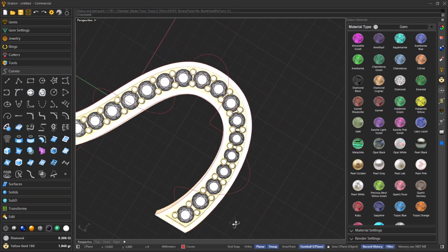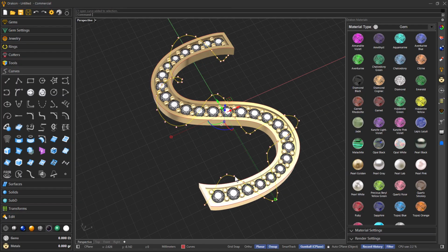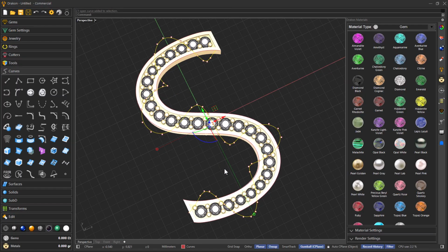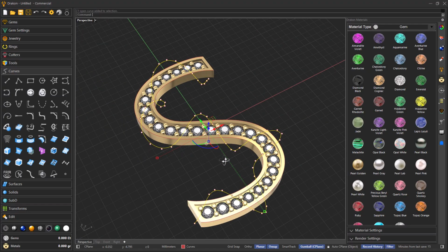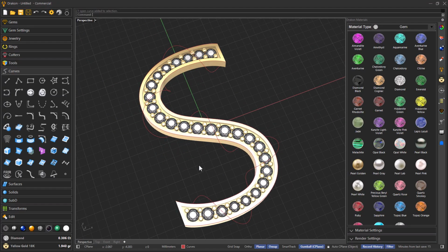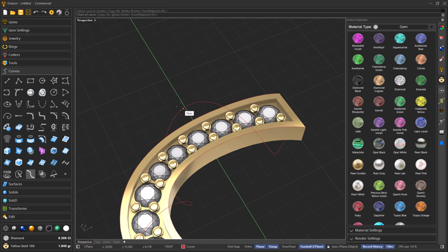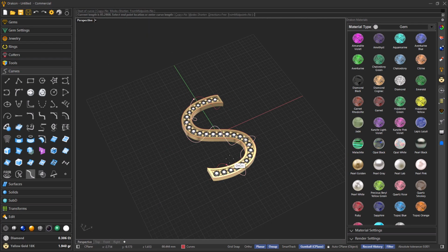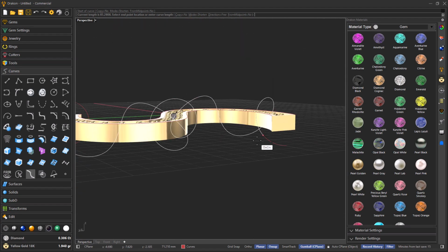It looks good. So what I'm going to do with this curve is to apply a serpent shape along, but not to the entire curve. What I'm going to do first is to use this subcurve command to define the start point. Maybe I will start, let's say, from here until somewhere in here.